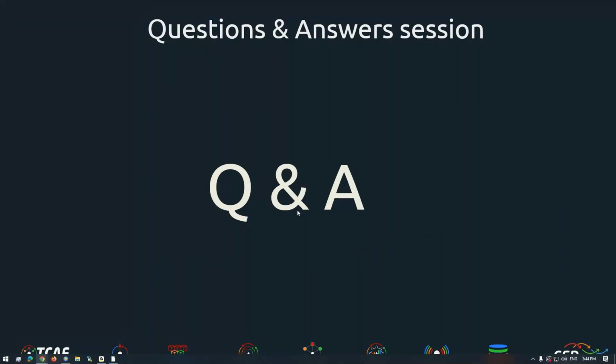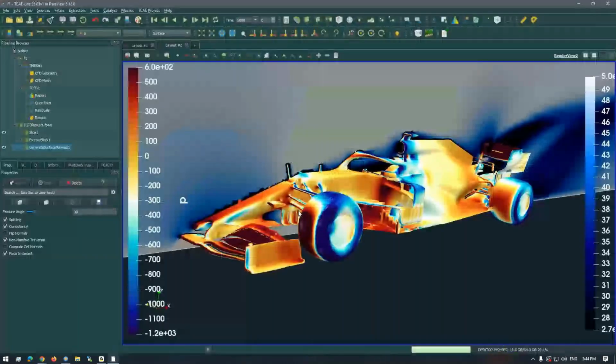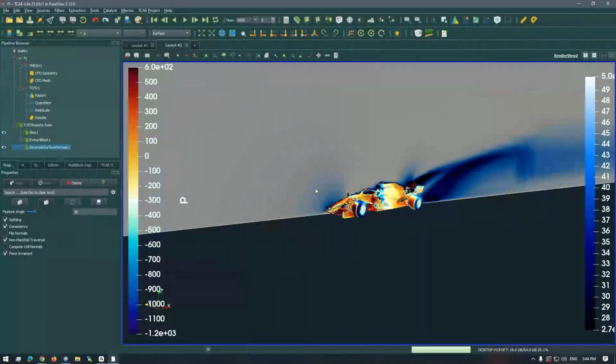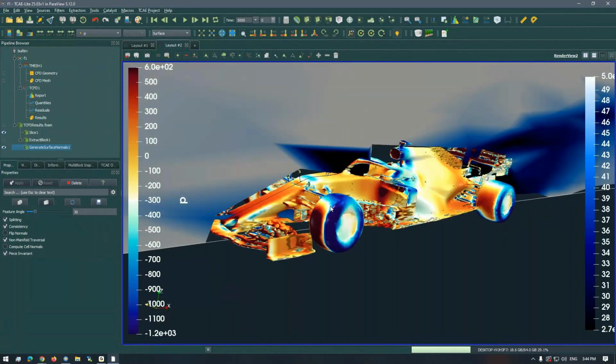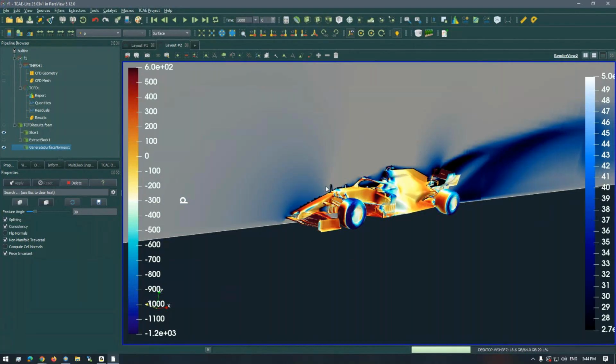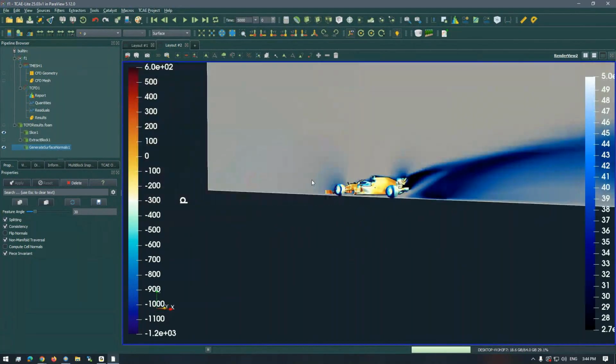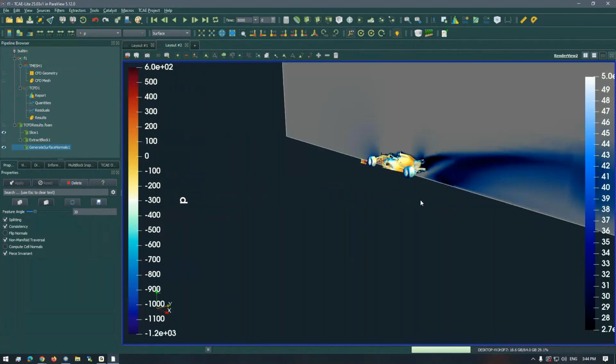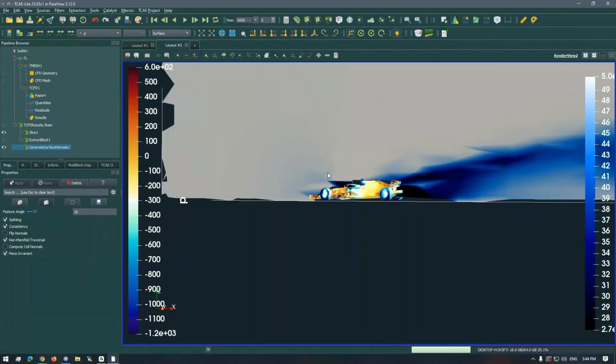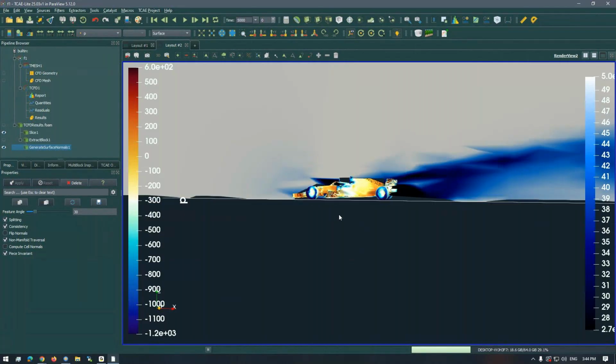And then, if it's in the expected range, you need to go more inside, for example, to check the mesh quality for all the details. You need to check, for example, if some quantities are bounded or not. So you need to go deeper and deeper if you would like to have the analysis in the sense of what is good and not good results. Sometimes if you do a benchmark and you would like to fit the measurement data, then you also need to think about how the data was measured.